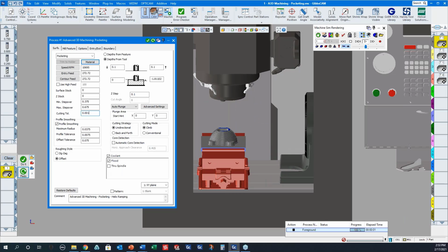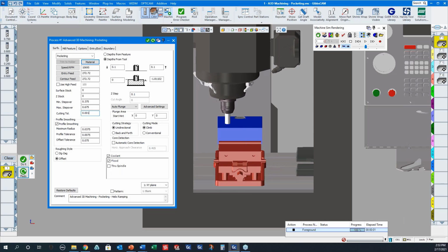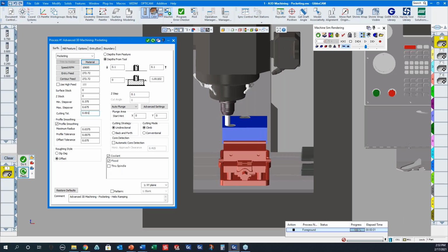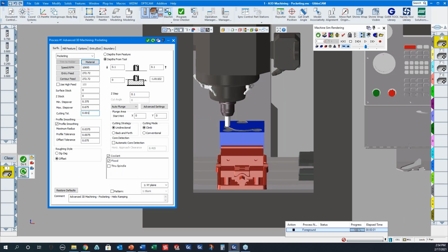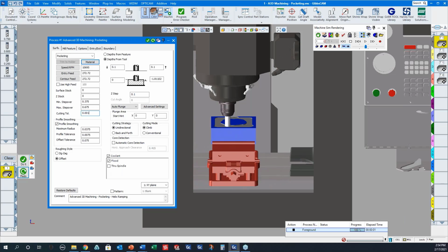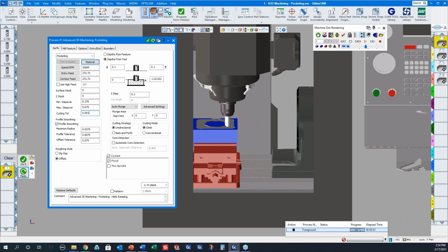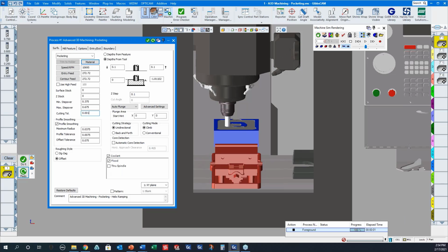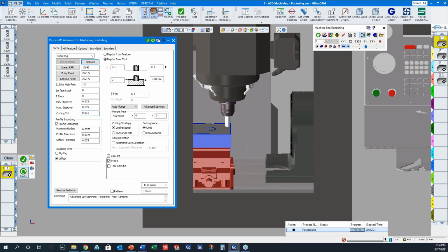So if you need to do that, you should contact your reseller and see what he could do about getting you upgraded to Advanced 3D, because 2.5D solids cannot cut true 3D toolpaths. Right, it can't generate X, Y, and Z toolpath all at the same time. Nope.